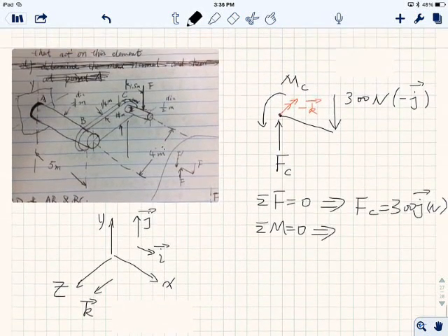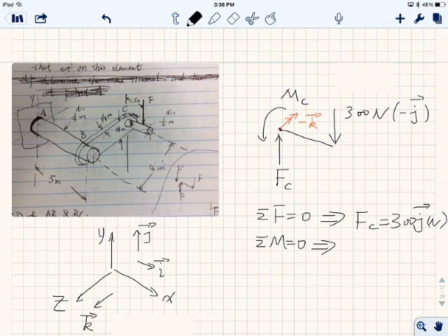All right, now let's look at this case. Again, keep the coordinates in mind: X, Y, and Z. X going this way, aligned with AB, Y going up, and Z going in that direction. So we only look at this small cylindrical ball over here. First things first, we start simple, right? So the force is 300 newtons. Of course, this Fc, the resultant force on point C, when you take this small ball out, will equal 300 newtons. That's easy to understand, right?